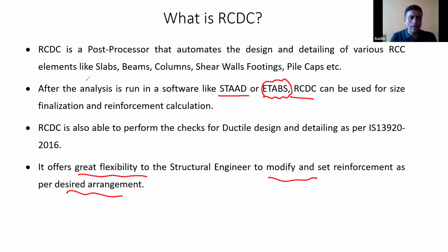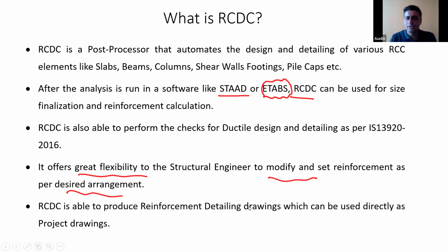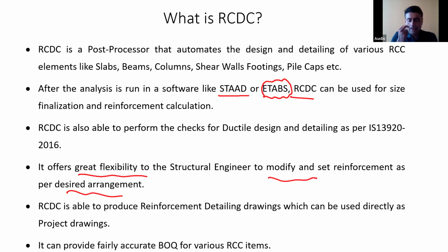And according to the set arrangement, RCDC will be able to give you the reinforcement detailing drawings, which you can also use directly as project drawings. And RCDC is also able to give you a good level of accurate BOQ for the various RCC items. So in this way, you can use RCDC to make your work faster, efficient, and easier, mainly for projects which need repetitive working.